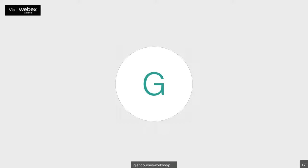Shadow region, like we created that mask, and that is the depositing because of this shadow. So it is a physical mask, and since it is vertical, there is no shadow of the mask. Shadow in the sense like it's a completely different thing, like where you create a shadow and deposit a nanostructure. That is a different technique known as glancing angle deposition. So here there is no shadow. Instead, there is a vertical deposition, and where there is a mask, there is no deposition, and where there is no mask, we have the deposition of the metal that defines the active area.